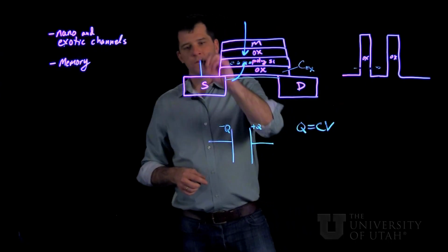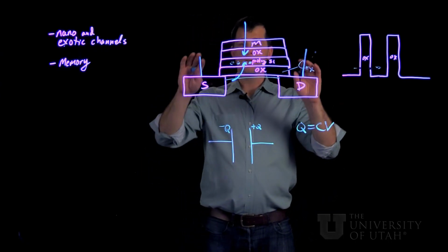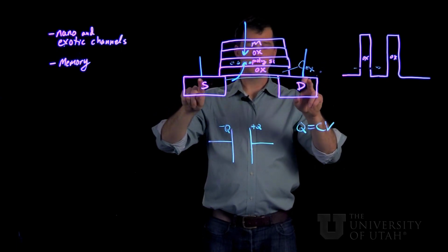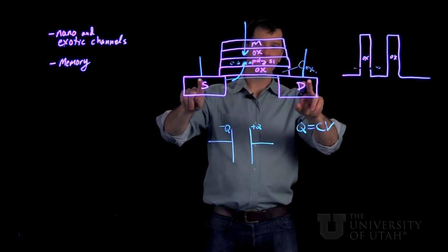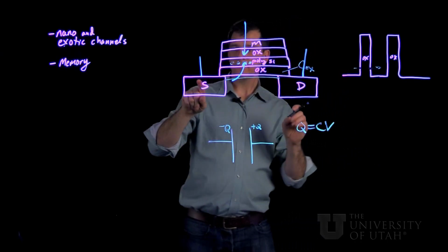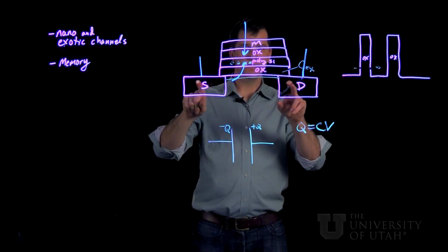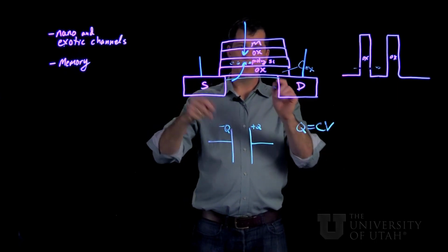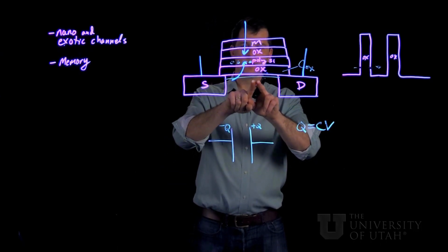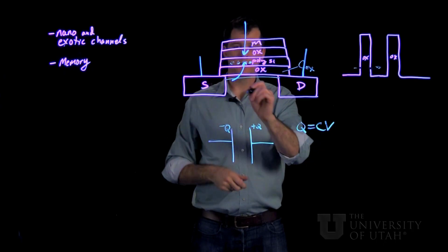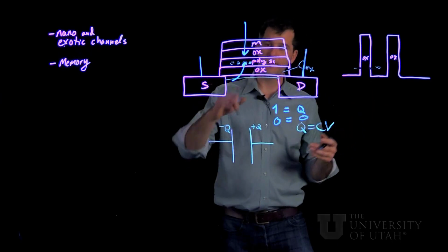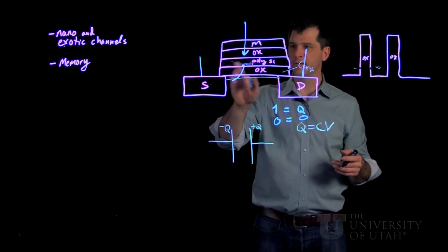So what this means is, by sending a test signal, trying to establish a connection between the source and drain, the controller can say, memory element number 4080, do you have a digital 1 or 0? So if there's charge here, there's an inversion layer in our N-channel MOSFET, and thus you get a digital 1. And a 0 would correspond to no inversion layer, meaning that there's no charge there.